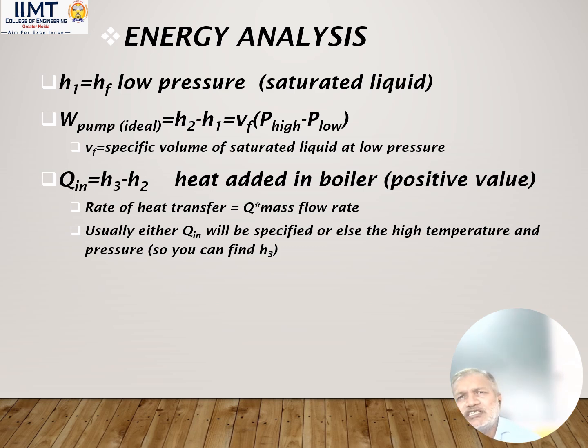Like the steam generated in the boiler, the steam generated is generally superheated, dry saturated, or even wet. So we know the condition, and from the table you can easily calculate it. Similarly, the expansion in the turbine is isentropic. So if you equate the entropy, you will find the dryness fraction, the condition at state 2, that is at the turbine exit. So you can also find H2. S3 can also be found, but H4 is after the compression, the pumping of the water.